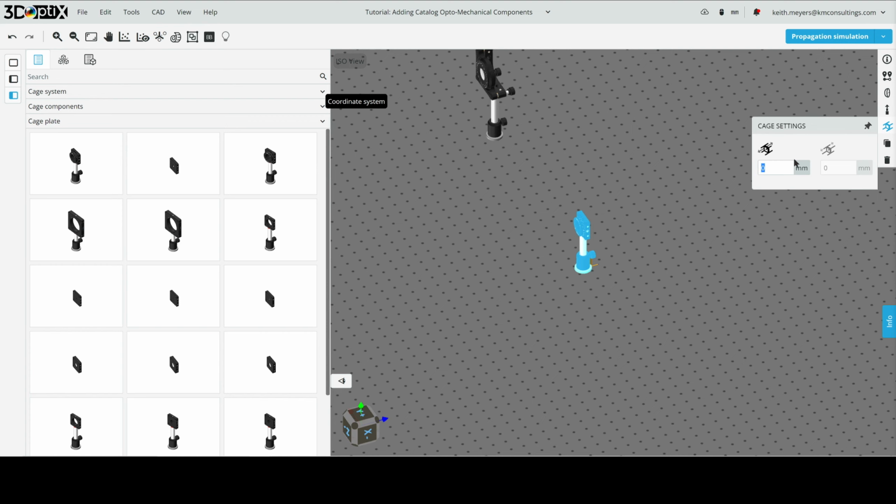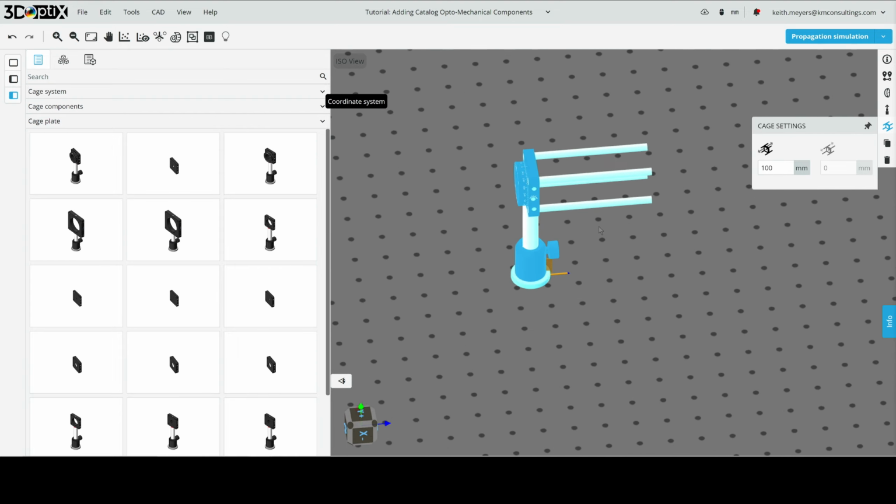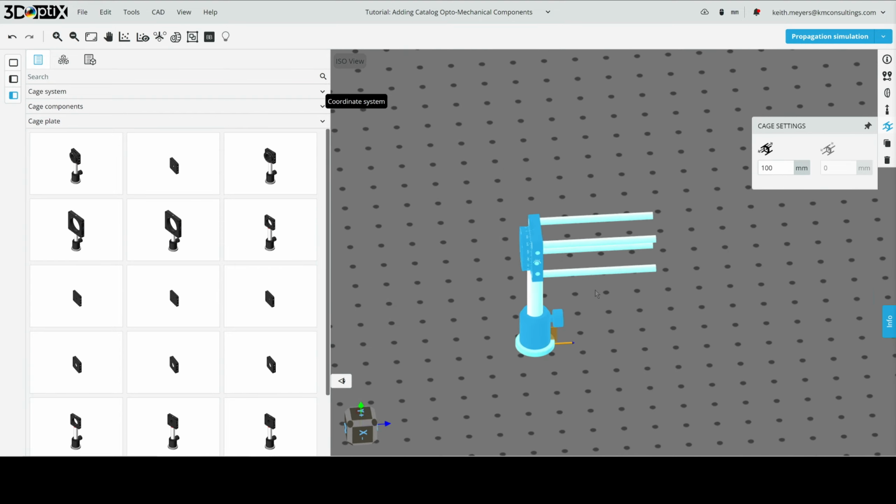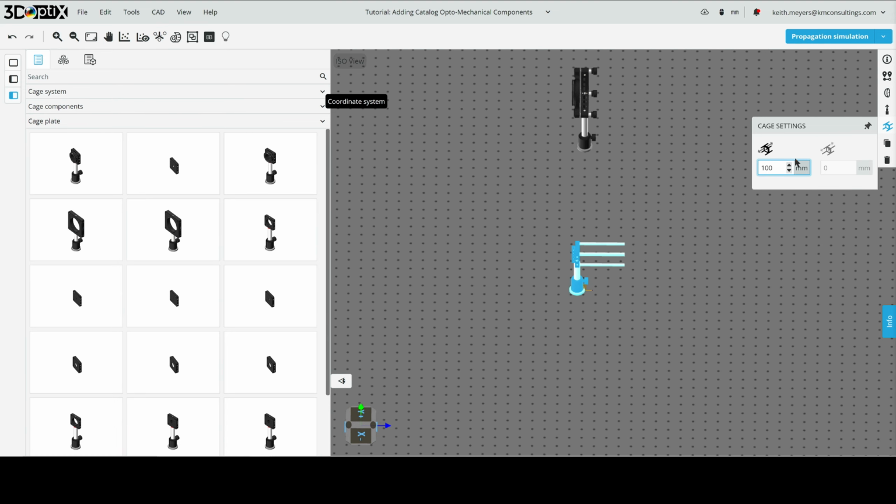So this is the length of the cage construction rods. And as you can see, they pop out of the back here. So we can use this as a cage system. Now, the cage will move by 12.5 millimeters, and you can remove them completely if you set them to 0. You can move them in steps of 12.5, and then you can maximize them to 635 millimeters. Let's move them back to 200 millimeters.